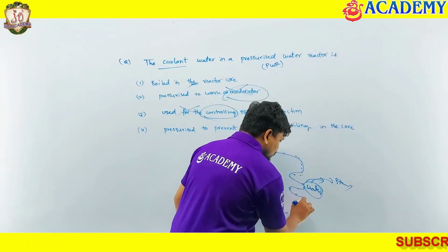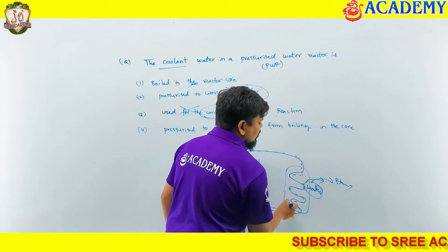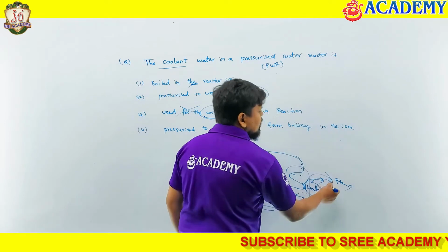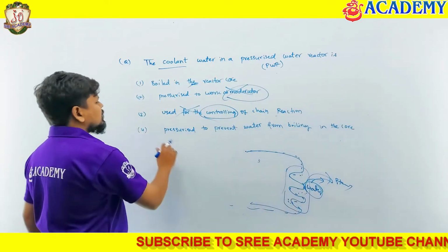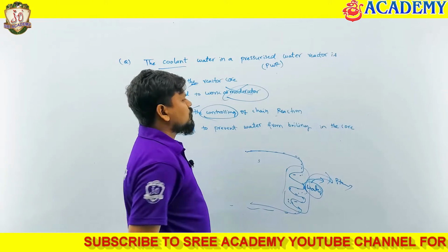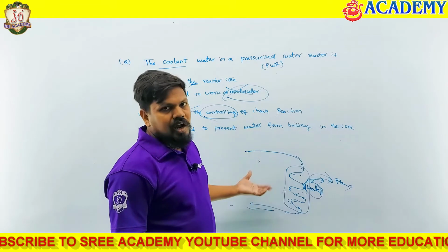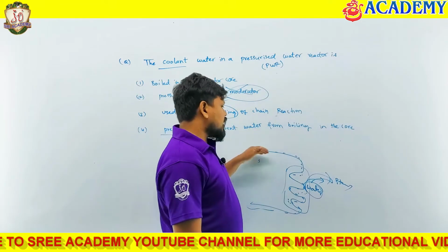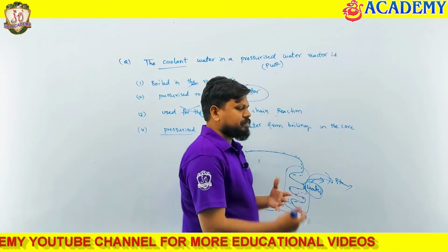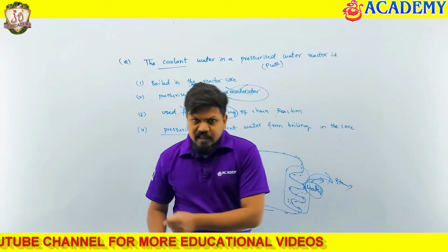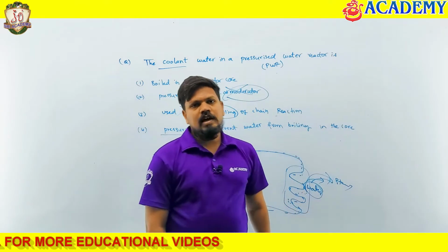It has to carry the heat into the heat exchanger. So whatever water is present here already, all this water will convert into steam. That's why the water is pressurized, to prevent the water from boiling in the core. Here it should not get boiled. It should not convert into steam, whatever is coolant. So it has to carry the heat from the reactor to the heat exchanger. So that is the application of this.